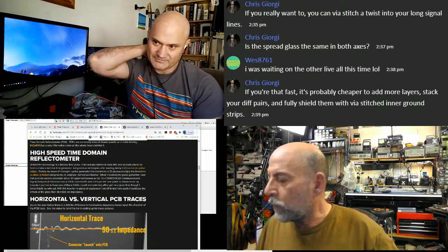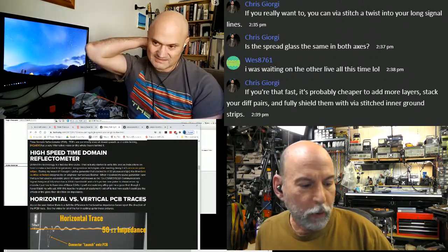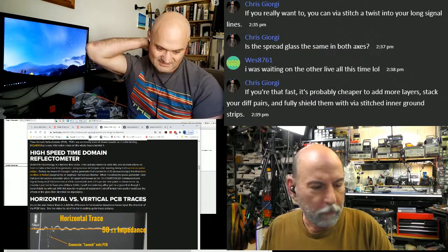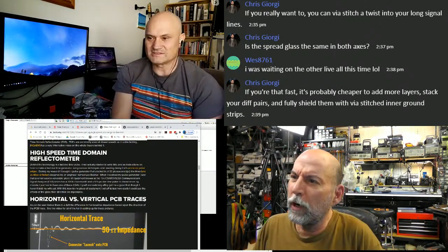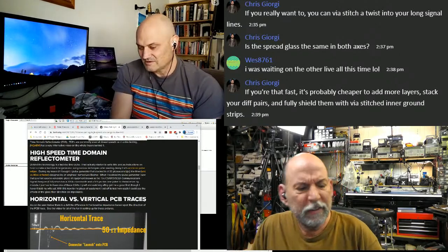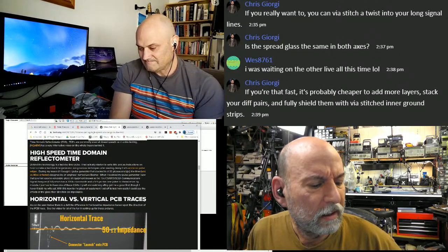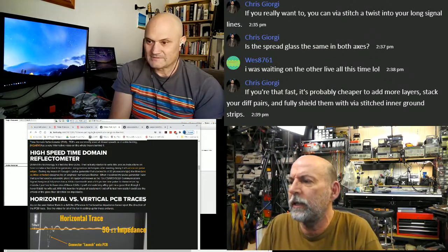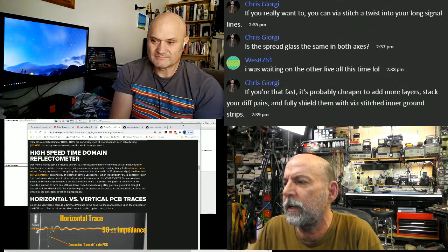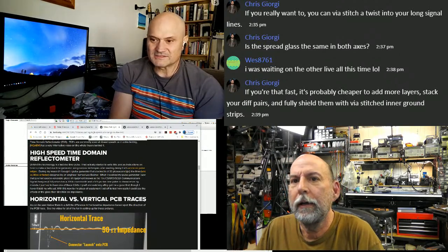No, that's fine. So how fast does it travel on a PC board, typically? It depends on the dielectric, but with the standard FR4 dielectric, it's about 6 inches to a nanosecond.